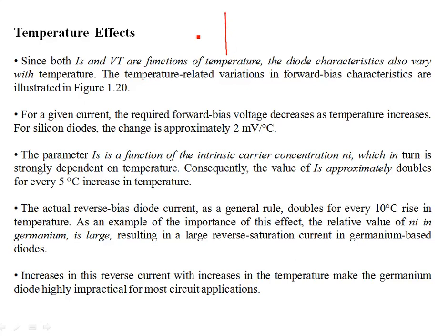Characteristics of the diode. You see, a diode is inherently a nonlinear electronic circuit device in which the IV characteristic is an exponential in the forward bias region, where you apply the external bias such that the VD positive terminal is connected to the P-type region and the negative terminal is connected to the N-type region. So the current that you derive, once VD is sufficiently large, greater than the barrier potential, is an exponential increase in the current of the diode. So it's a nonlinear device, okay?